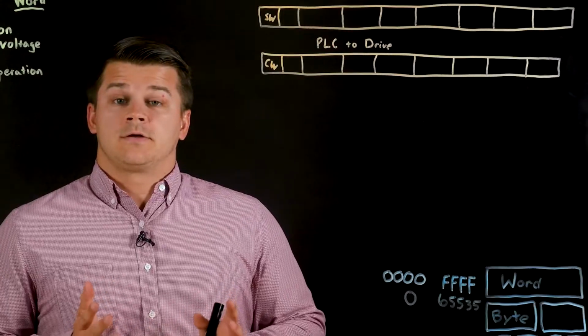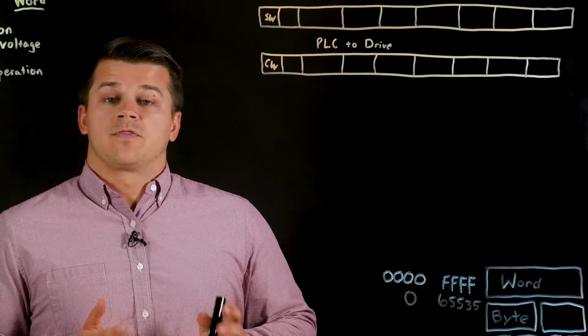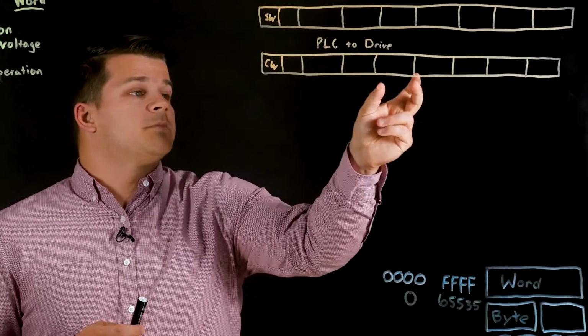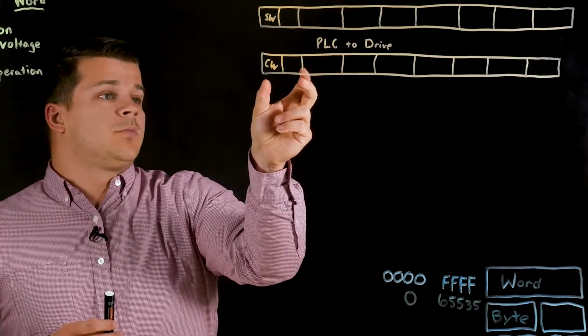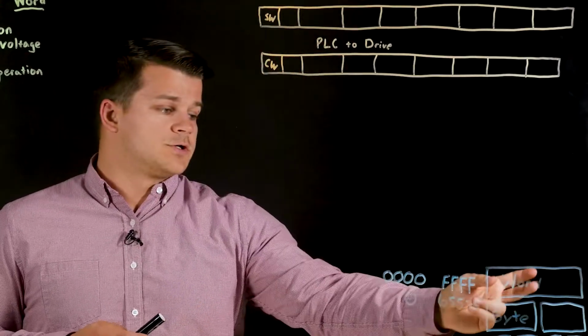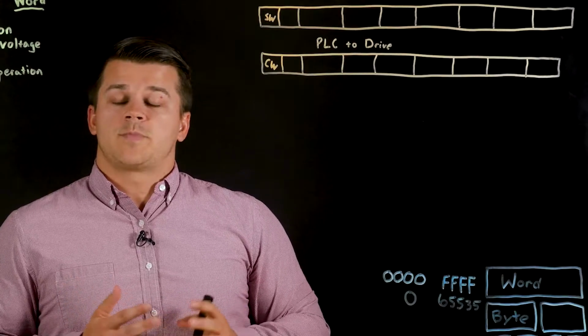For the fastest cycle time in the EtherCAT protocol, it supports up to 8 objects and 32 bytes. Shown here, each rectangle is 1 object and 4 bytes or double word until you get to here, where the control word and the status word, as we know, are just a word and 2 bytes. Thus, more bytes are available to be used by other objects.